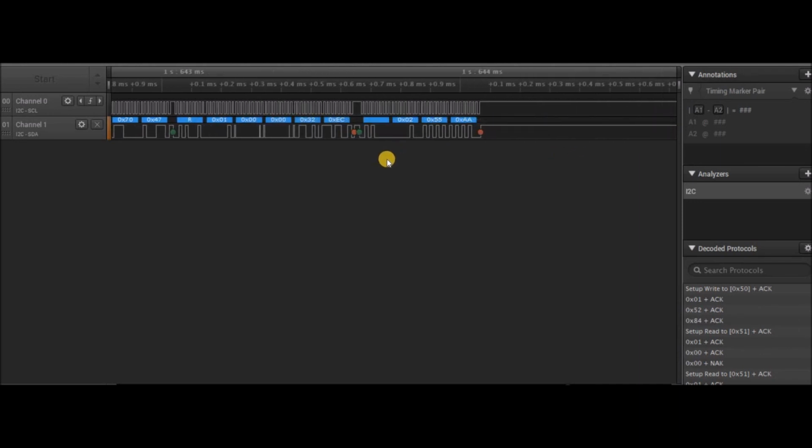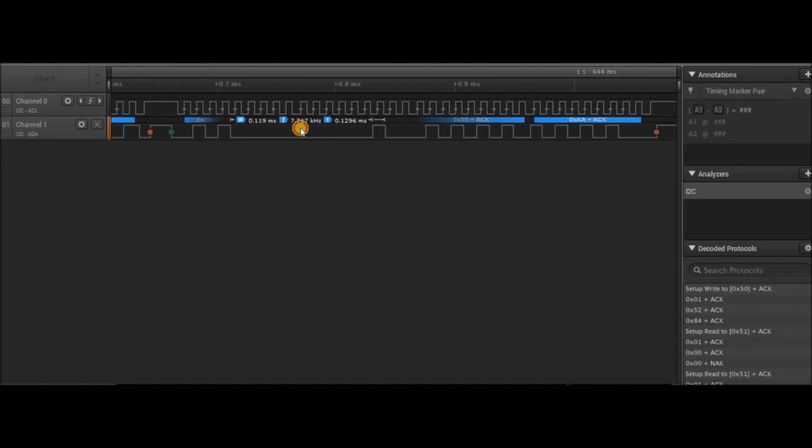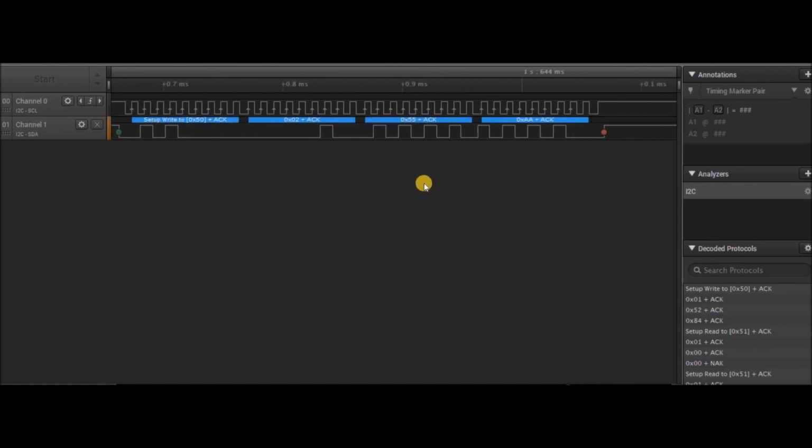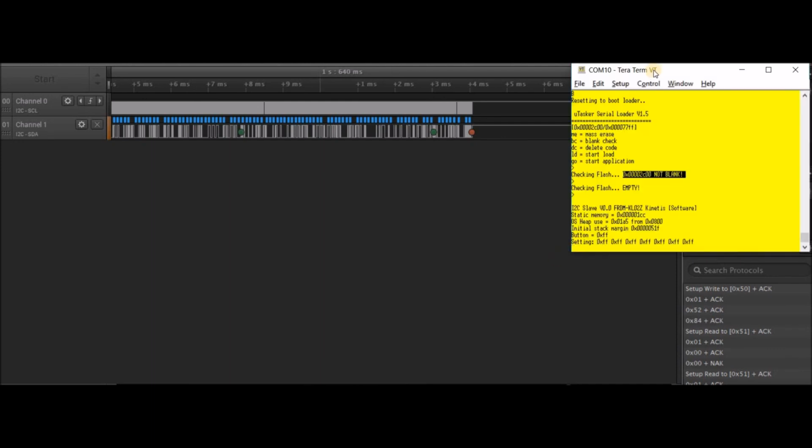Now, because the master has now sent all of its program, it sends the write with command 2, which is reset, with 55AA just as an extended key, just to make sure that we really wanted that command to be executed, and that's when the reset will then take place, and the slave device then reboots.